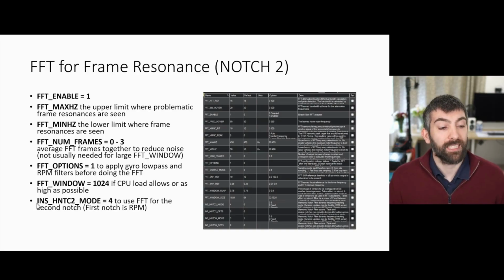And then you're going to want to set INS_HNTC2_MODE equals 4. Now that will set the second bank of harmonic filters to use the FFT to drive those second bank of harmonic notch filters.